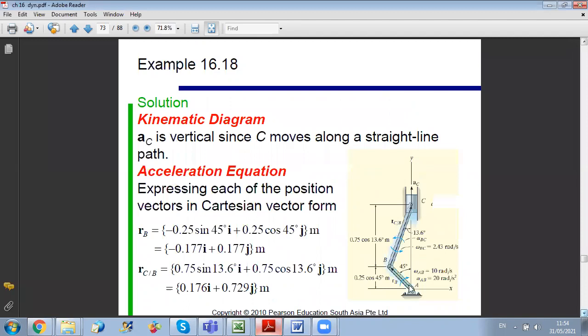So as we said, look, the first step, they find the vectors needed, okay? So since you need vector BC, you will decompose it into two components. So you need vector CB, and also you need vector AB, in case you want to use the vectorial method to get acceleration of B, okay? So here they got the vectors required for the calculation, the position vectors AB and BC, as a first step.